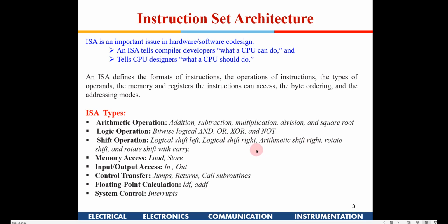From the left-hand side, from the MSB side, for logical shift it is 0. For arithmetic shift it will be the sign. If the MSB is 0, zeros will be inserted. If it is 1, 1s will be inserted.